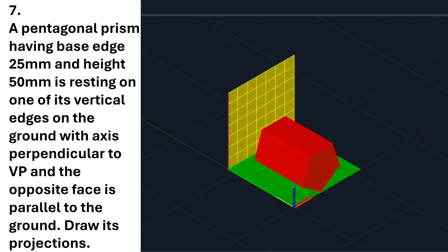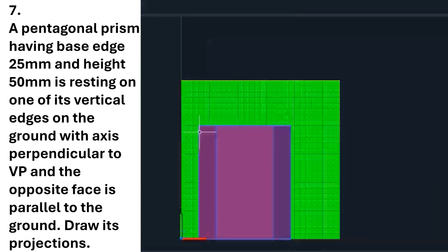If you see the top view again, now these three faces will be visible, and the remaining two faces which are down will not be visible. So the line joining the leftmost corner and rightmost corner, the top faces will be visible and the bottom faces will not be visible. So then we can draw the top view. The top view will be looking like this.